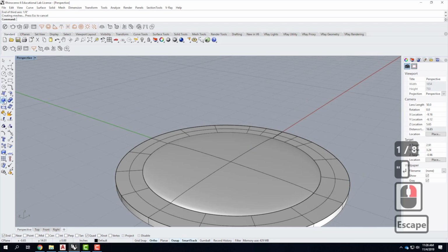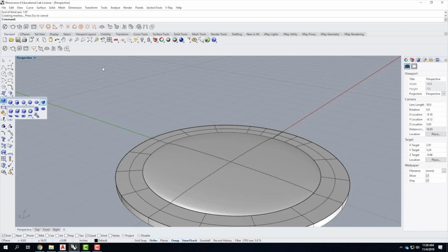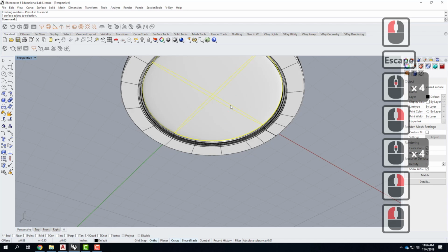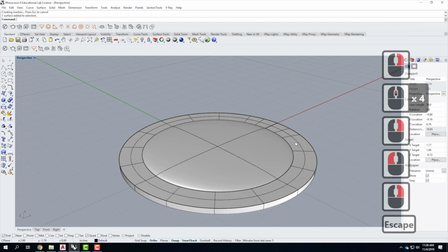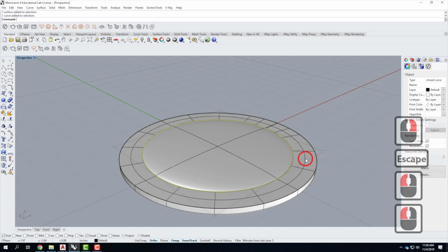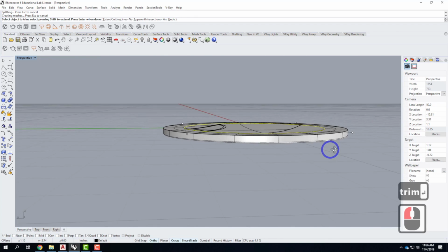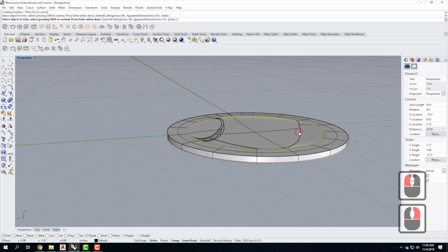It's an ellipsoid. It's underneath the cube here. It's that one. And so we can see that it has a slight little bit of an arc to it on this side. I don't need the whole arc, though. I don't need it on the back side. I'd rather keep that flat. So I'll select the curve that I had here, and I'll trim the back half off. At least I hope I'll trim the back half off.